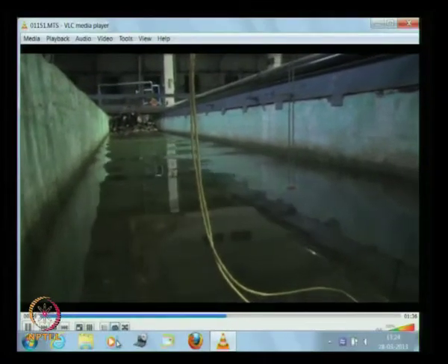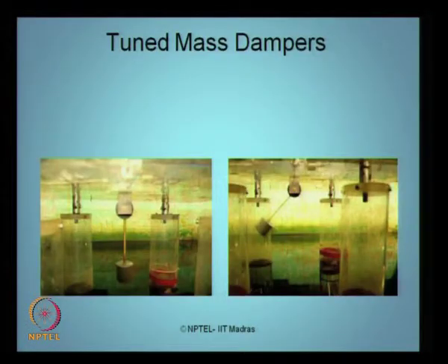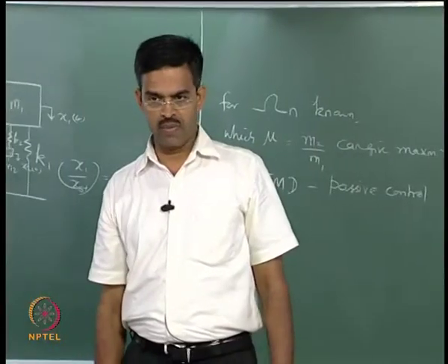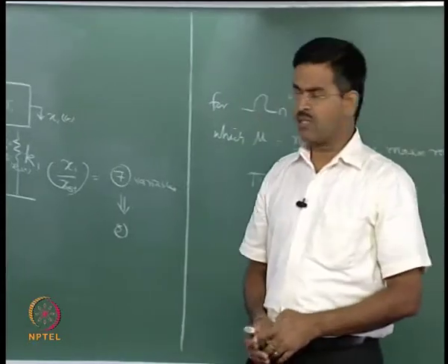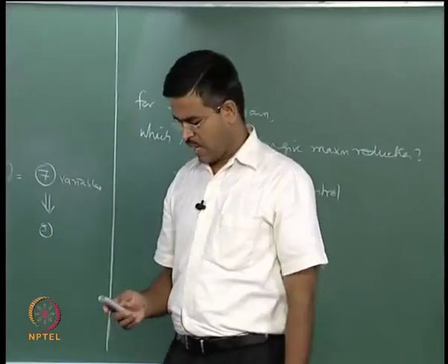Any questions here? So, this was the experimental setup we had, and we have seen the videos of how the experiment was done. The left hand side image shows the static condition of the installed model, whereas the right hand side shows the maximum displacement of the secondary mass system at omega equals sigma, when the primary system is supposed to resonate to the maximum response, okay. It is not happening here because of the advantage of the secondary mass attached. It is a very simple algorithm tried, and let us see the benefits.